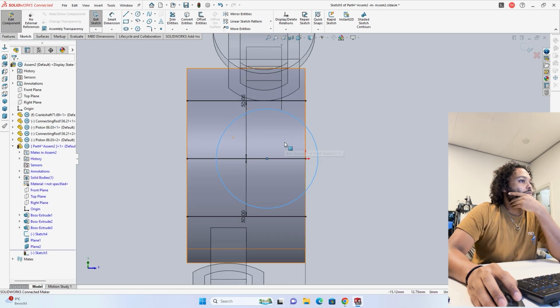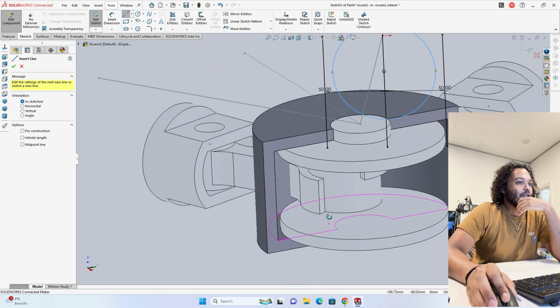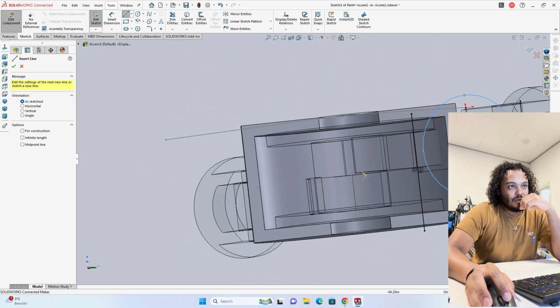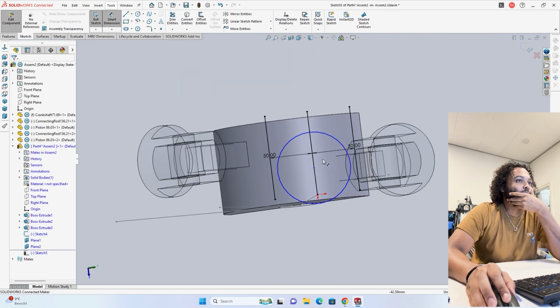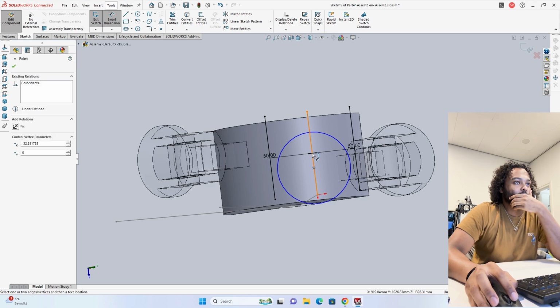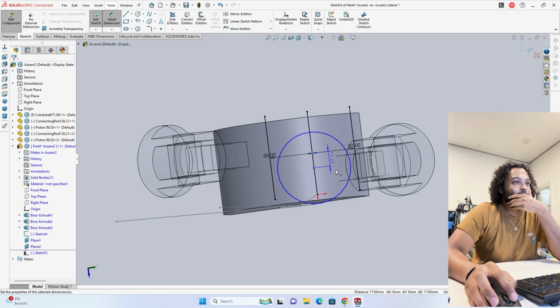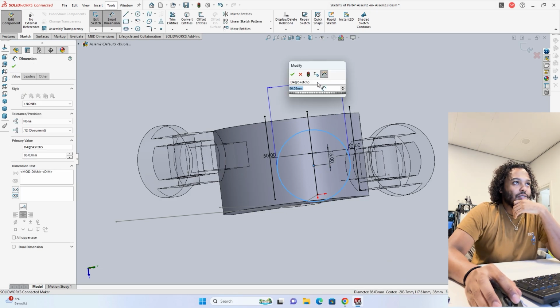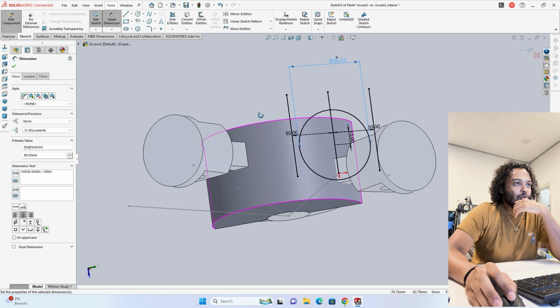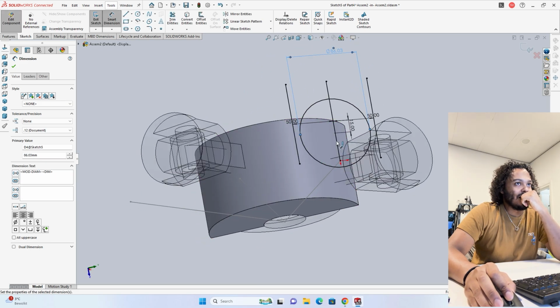There you go. And we also know that from the center of the block, if you look at where the connecting rods connect, they actually have a 15 millimeter offset to one side and the other for it to start the section with the cylinder. So from the center of the section to the center of this line, I'm going to make a 15 millimeter offset. And as you can see, the dimensions seem to change a little bit. So that is basically what that will be.